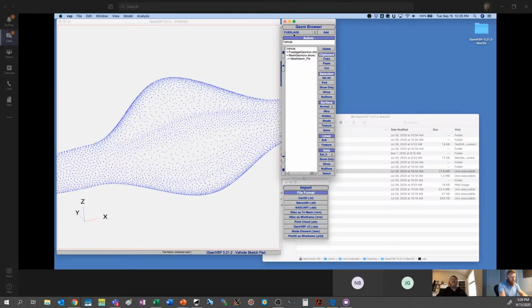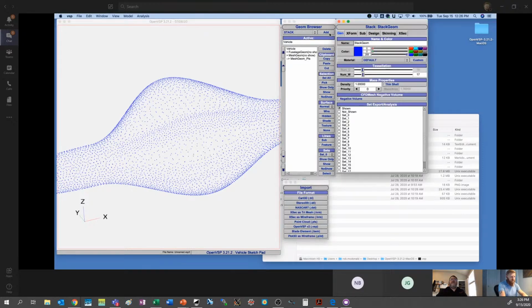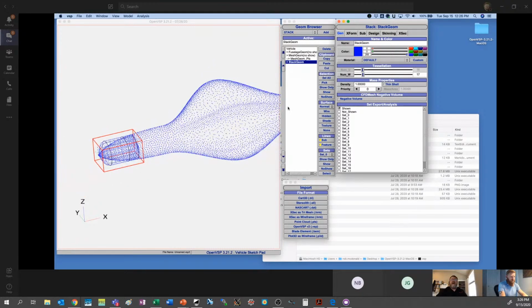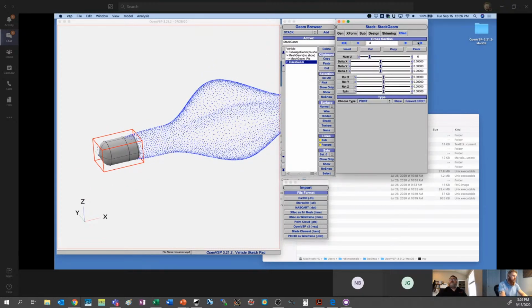And so just for fun, to give you an idea of what I'm thinking about, we're going to add a stack. We'll shade it right now, but I'm actually going to go to the end of the stack, and we're going to delete the first couple of cross sections, and we'll go to the beginning, and we should be able to cut it down to, okay, we're down to the minimum number. We'll make this one a circle and just open it up a little.